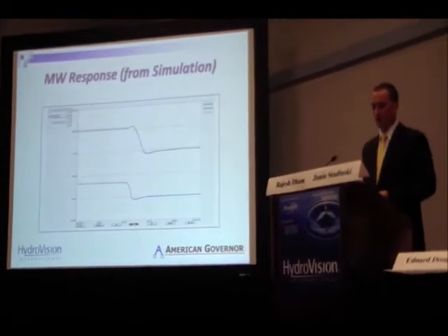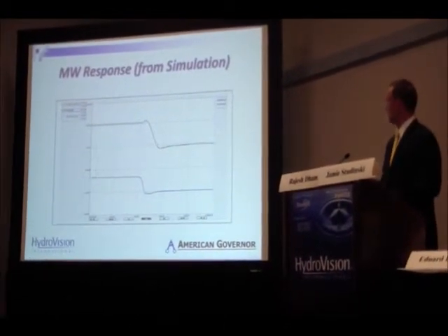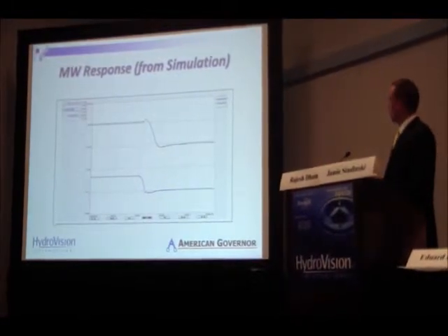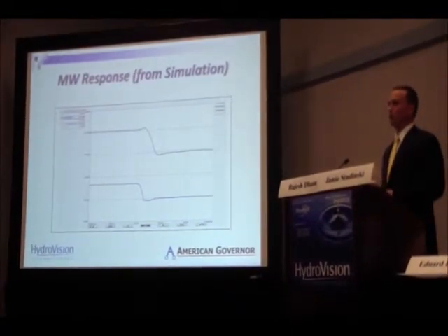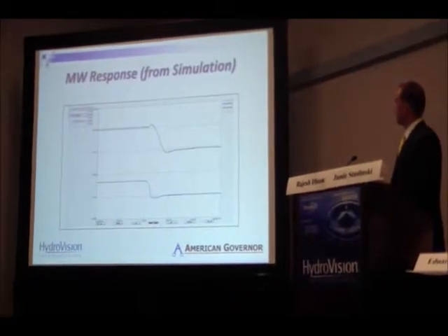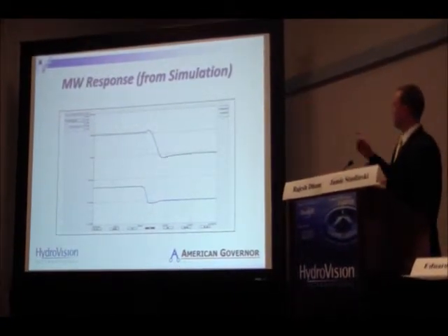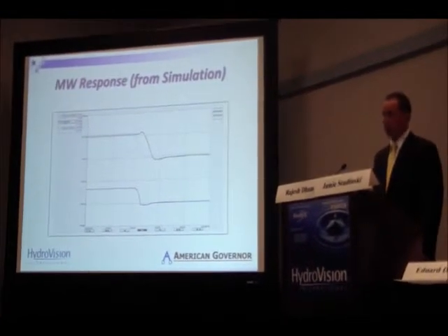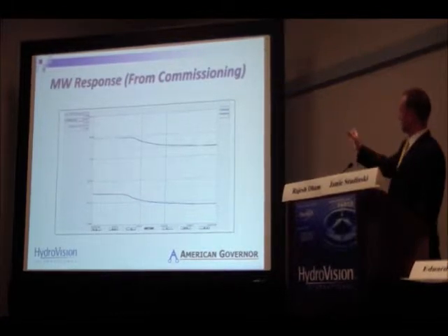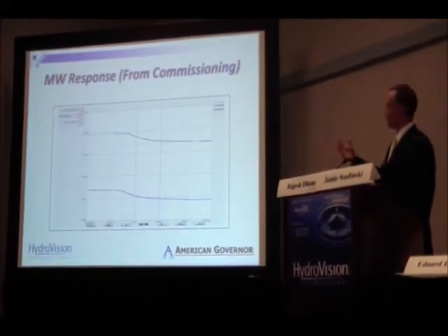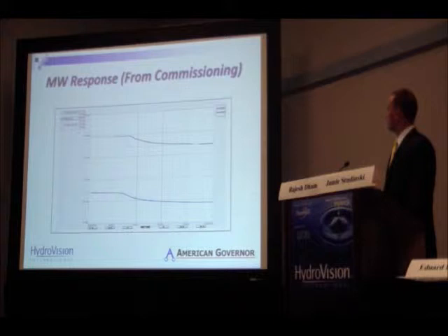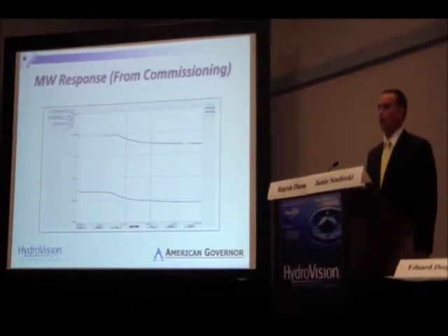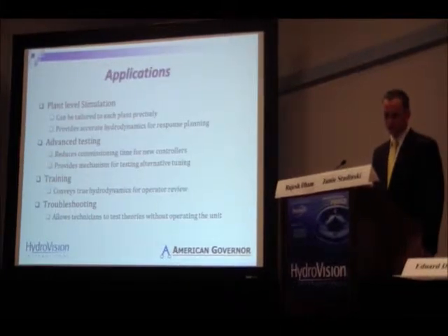And in the same way, we have a megawatt response from simulation. Again, we're a little underdamped. Some of our underlying tuning parameters are not exact due to time and cost considerations as well. We were able to develop something that was controlling power. We were able to regulate to a certain degree of effectiveness. But of course, albeit on a different time scale, we can see that after the commissioning, we had made a few fine tweaks and were able to develop a system that was controlling power most effectively.